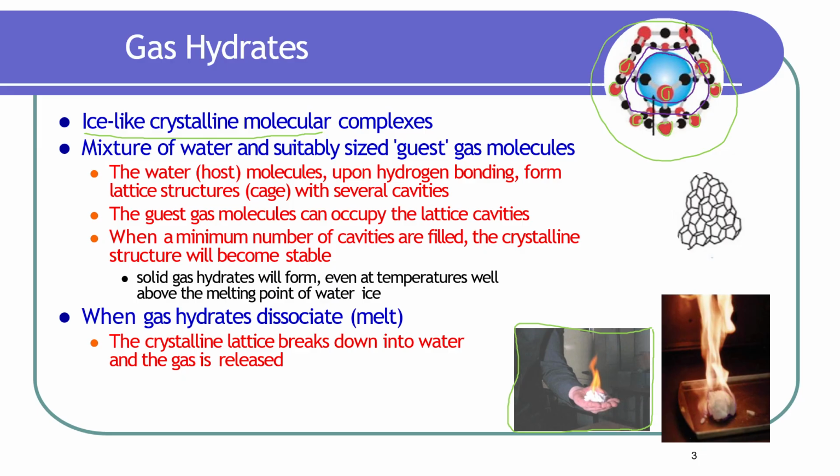So when we talk about gas hydrate, we are talking mainly about two things. We are talking about water molecules that are bonded to each other through chemical bonding, and specifically hydrogen bonding, and then we are talking about the guest molecule, which is entrapped inside the cage, or the vacant space, and which is normally the gas, normally the CH4 or the propane or the ethane, but more specifically, the common one is the CH4.